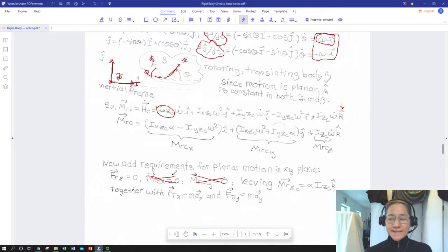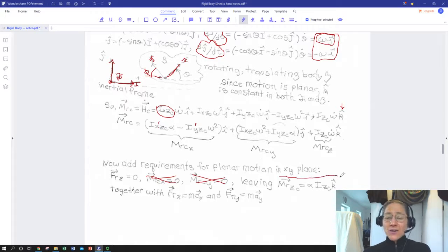And we can't twist it or rotate it such that it would no longer be moving in that same plane. So the terms that include all of our products of inertia have to be 0 by definition if we are restricting ourselves to planar motion. So we simplify our entire relationship between angular momentum and total net applied moment, or resultant moment, for planar motion of a rigid body as just being the sum of the moments in the z direction about the center of mass is omega dot,